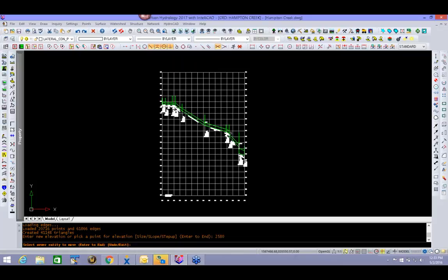I draw all of my storm drainage and my sanitary all in one profile, so that when you see mine, you're checking for service clearance. In this case, when we do lateral checks or crossing checks, it's only at the crossing of the pipes. If you have to come out of the top of a sewer line with a service that goes at 1% underneath storm drainage, you still have to modify that yourself and watch that yourself. But I'm working on it.